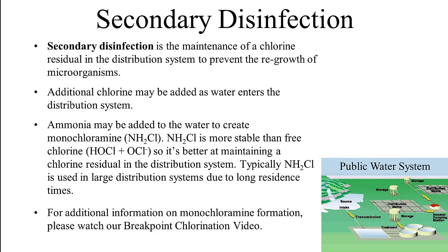With secondary disinfection, the chlorine concentration is managed to ensure pathogens are prohibited from reinfecting the water in the distribution system. Large systems can have thousands of miles of pipeline and have long residence time, or the time between when the water leaves the treatment plant and when it reaches the tap. In some utilities, the residence time can be several weeks. Therefore, it is important to ensure the water continues to be safe.